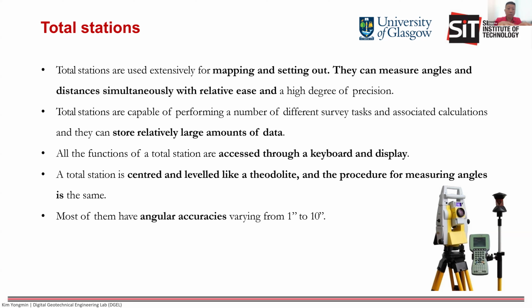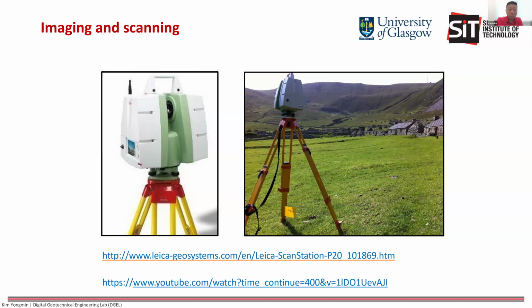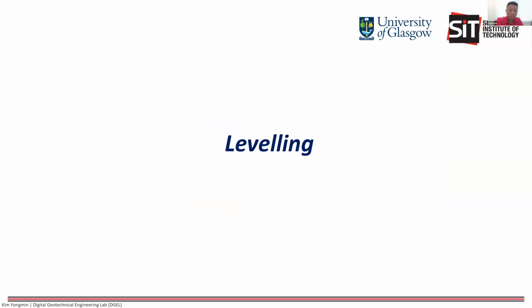The setting up procedure is the same as setting up the theodolite, and the measuring procedure is also the same. The accuracy of most total stations varies from 1 second to 10 seconds. So these are some total station instruments. Of course, just now I think Shen also showed the TS06 that you are going to use, which is a more advanced version.